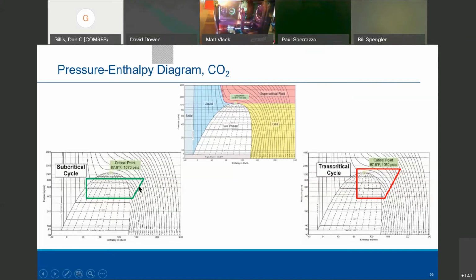I touched on this a couple weeks ago. I don't know how many of you benefited from it, but just in case there's somebody on the line that doesn't understand these, I'm going to walk through this real quick. This line indicates your compressor. This line on an enthalpy chart indicates your condenser. When you're coming vertically down, this is showing you coming through the metering device, and then this is our evaporator, okay?